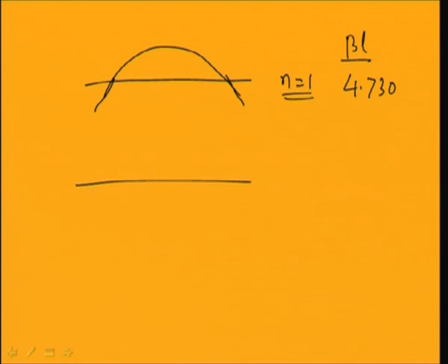So you can plot it like this, and you can see that there is a node here, a node here, and also a node here. In the first mode you have two nodes, so at these 2 points on the beam there is no vibration. For the second mode, you can see that there are 3 points at which there is no vibration.